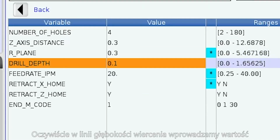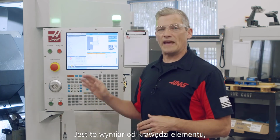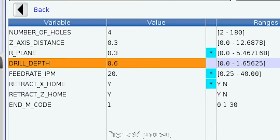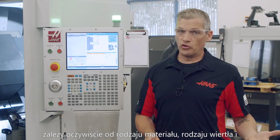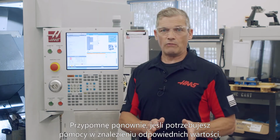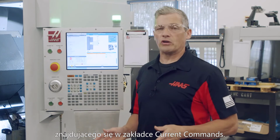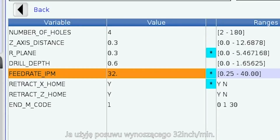The drill depth line, of course, sets the depth you'll be drilling to. It's the dimension from the edge of the part to the bottom of the hole. The drill depth on the print calls for a 0.6 depth, so I'll enter 0.6. The feed rate value will of course depend on your workpiece material, the drill type, and desired chip load. Once again, if you need help finding recommended values, you can use the speeds and feeds calculator on the current command screen. I'll be using a feed rate of 32 inches per minute.